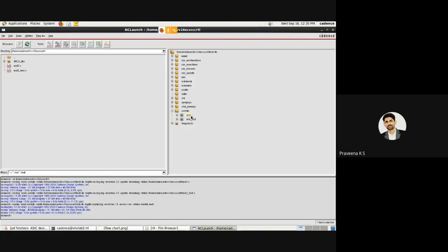Fine. So basically, in this case, we have written an AND gate, so it will try to recognize the AND gate and its RTL structure. Fine. For that, we have to elaborate the design. Again, elaborating will have a lot of operations, so I'll tell you in detail once we go for synthesis, what all the things are that we do in elaborate design. So for AND we did the elaboration. Again for AND test also, we have to do the same.